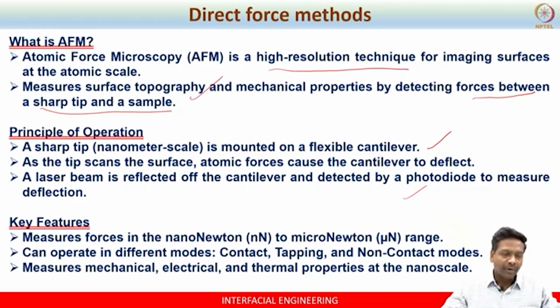Some of the key features of this technique: you can measure forces in the range between nanonewton to micronewton, similar to the range obtained using the SFA. This technique can be operated in 3 different modes: contact mode, tapping mode, and non-contact mode.